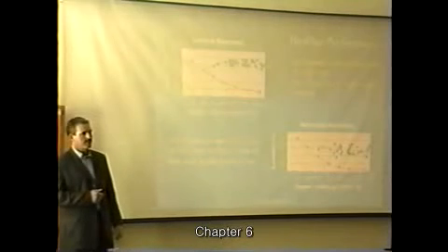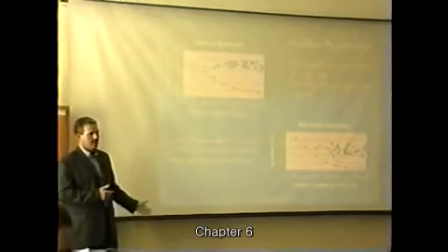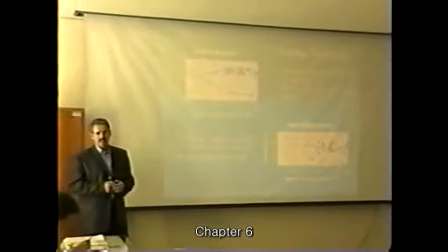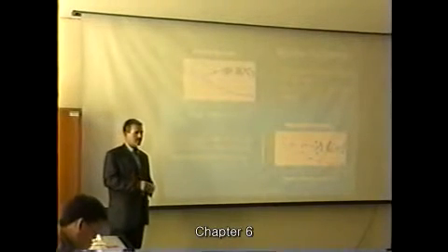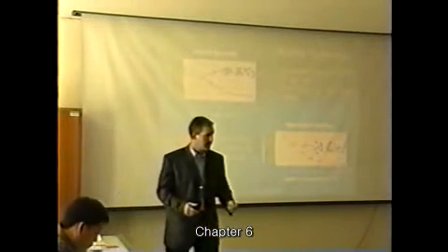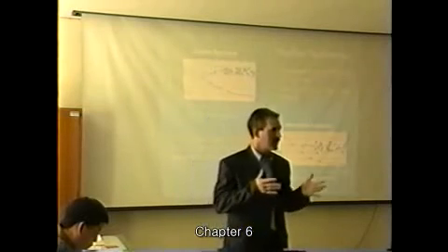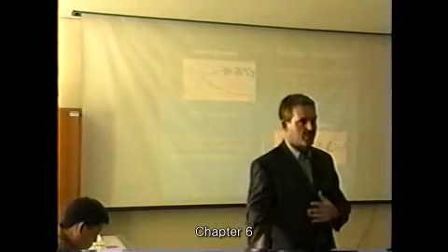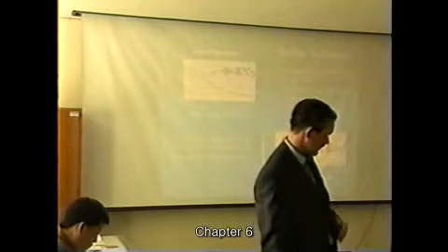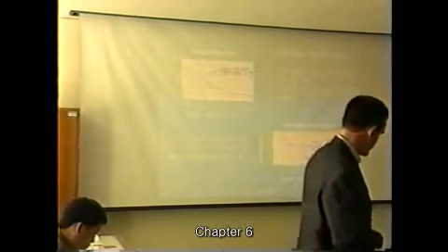We have a phenomenal amount of reduced sludge production, and it's been quantified as 70% humus sludge. That is humus sludge which you don't have to process through an anaerobic digester. It's sludge you don't have to throw into a drying bed or have to incinerate, as you have to do.